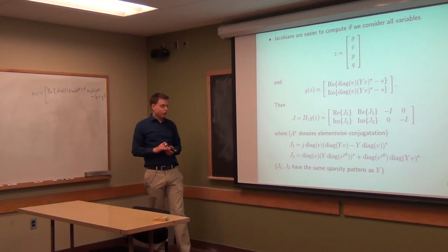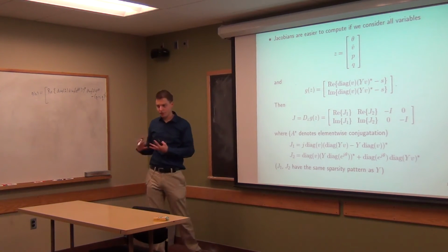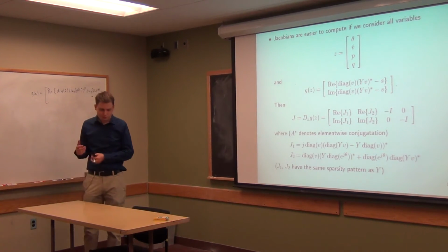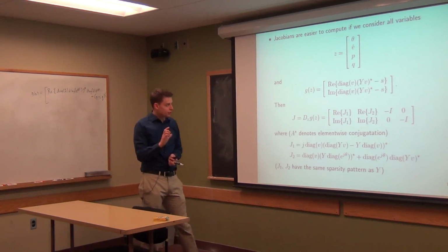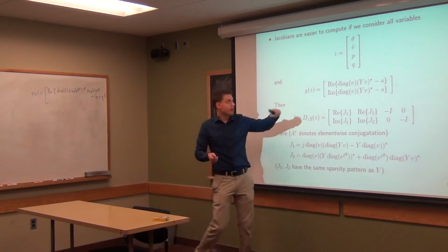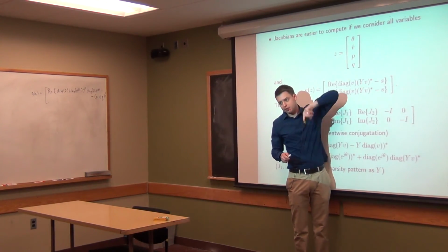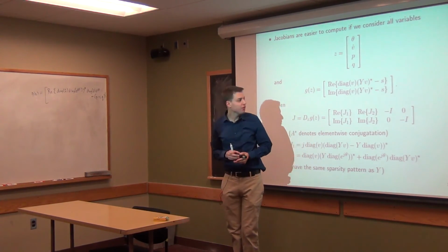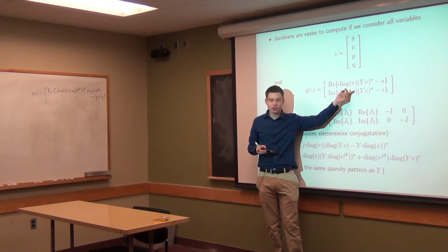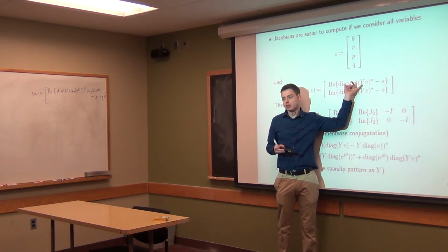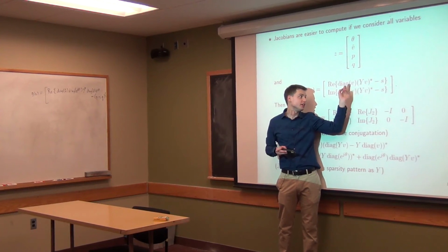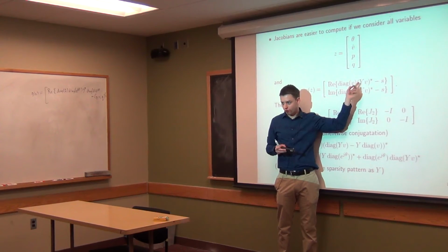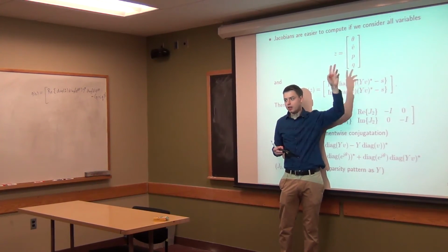The physical meaning of the Jacobians is that they're about derivatives. They are a matrix of element-wise derivatives. Physically, they're saying that if you change this entry a little bit, if you change theta 1, the voltage angle, a little bit, how will that change G, the output, which in this case is the mismatch between the power computed as it should hold for power flow and the power that you have assigned here.